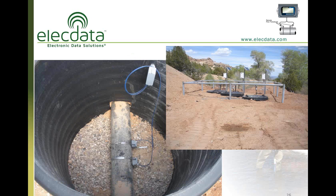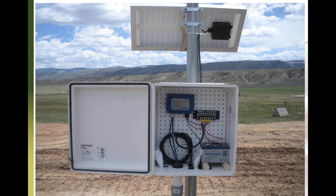This is a very well done irrigation application. The large picture on the left shows the sensors attached to the pipe in a correct side orientation. You can see that the sensor cable is routed up through some conduit where it goes up on the surface and terminates into a weatherproof enclosure that houses the 12-volt DC battery, a regulator, and then the UTM10 flow meter is mounted to the back plate of the enclosure. And you can see the whole system is powered by a solar panel maintaining the charge on the battery. So this is kind of typical for our agriculture and irrigation customers that don't have AC power at their sites.